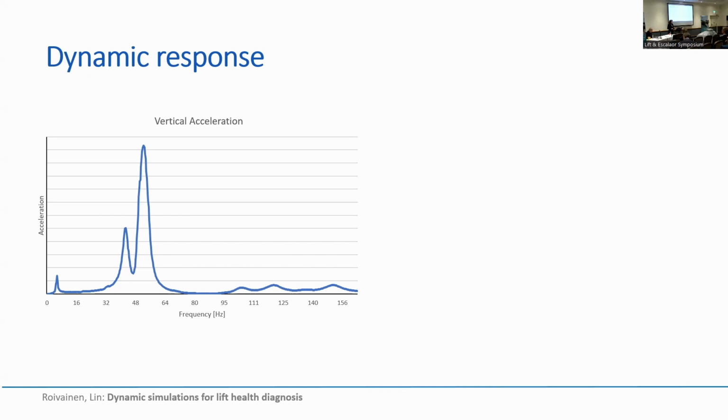For this meshless solution, we had 2 steps. In the first step, we calculated the eigenfrequencies, which are the frequencies that need very small excitation to have a huge response. And then in the second step, we rank these eigenfrequencies by sweeping an excitation with a very small increment during the frequency range of interest. So in this case, we had a vertical excitation swept with 1 Hertz between 0 and 160 Hertz. And we had a graph like this.